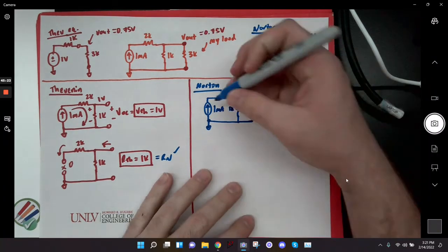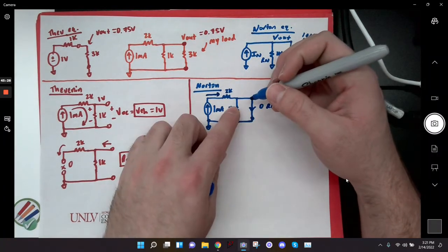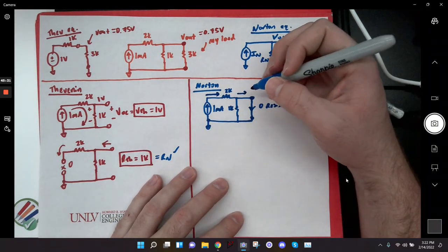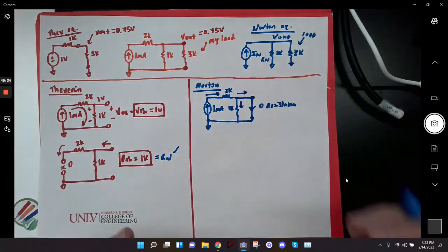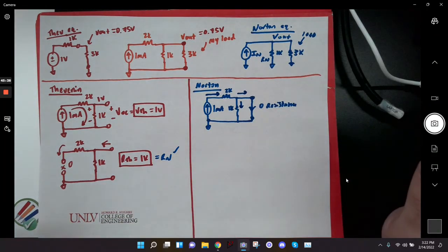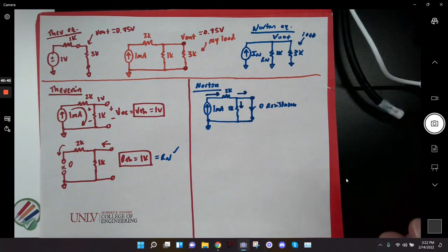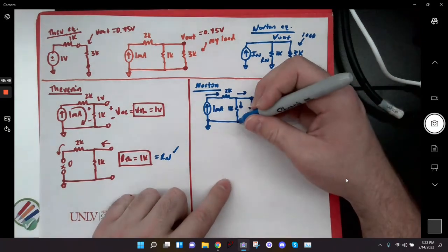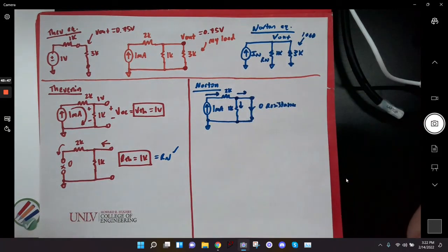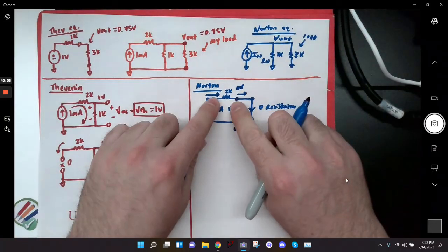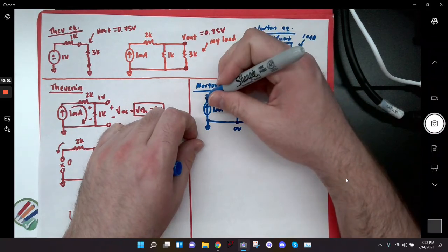Basically, my current's going to flow through this 2K, and then it's going to see 2 paths, right? It's going to see the path with absolutely no resistance, and it's going to see the path with resistance, and it's only going to go through the path with no resistance. So all of the current flows basically around that 1K. None of it will flow through the 1K. Another way you can see it is that I just shorted both sides of the 1K to ground, right? So both sides are at the same voltage, which means no current will flow through it, right? Does everybody see that? I have 0 volts here, I have 0 volts here. So current will flow through the 2K because I don't have 0 volts here, I have some voltage here, we don't know what it is.